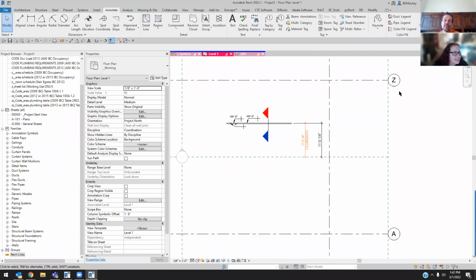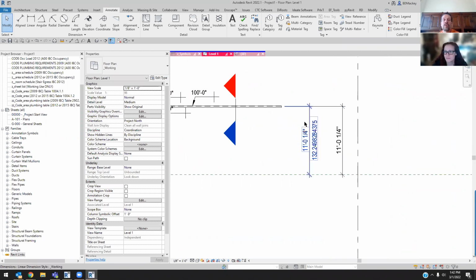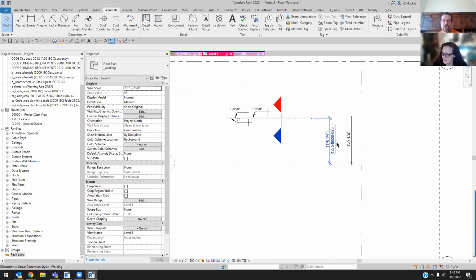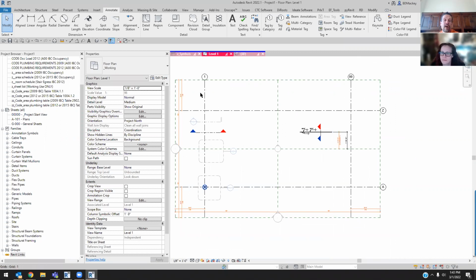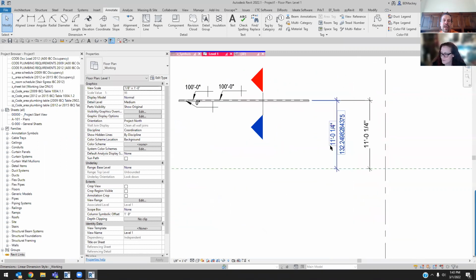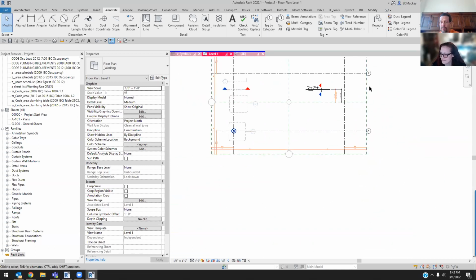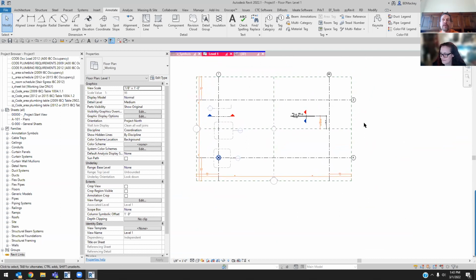And Sean was arguing on the 256 annoyances. And Sean, the reason why I care about this is when you start ending up in situations like this, I literally had this problem happen where somebody traced an AutoCAD file and every single grid dimensioned 20 feet. But at the end we got done, it was 20 feet some plus a half of an inch, right? So it was like 2,000 feet, 1/2 inch or whatever the number was. So there was that extra half of an inch because every single one of these was 20 feet, 0.0001. And by the end of it was a very large building. There was a half of an inch bust.